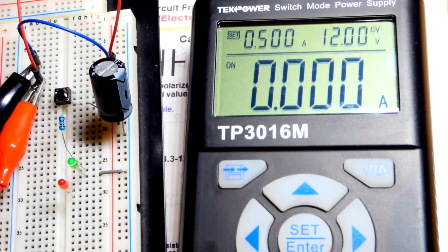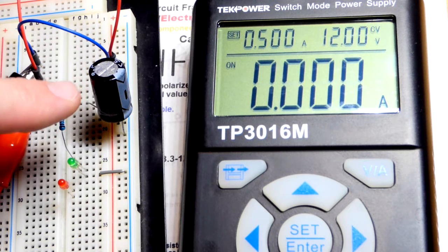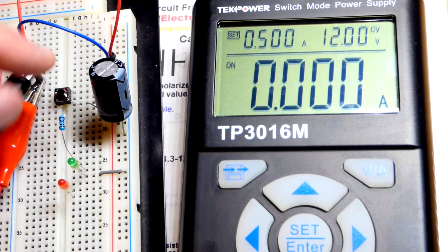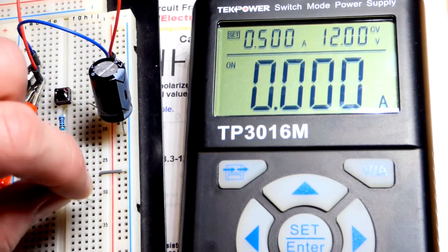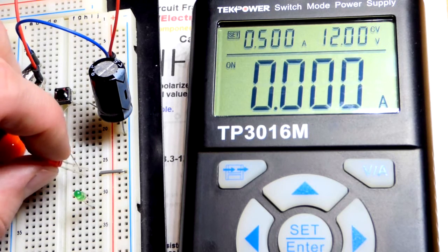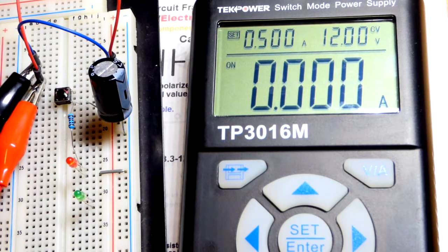The LED drops about 3 volts, and so it's going to probably discharge 9 volts down to 3 volts, and then probably level off somewhere around there. So maybe 2.5 or something. We could take those measurements later and see exact values. Now let's compare that with the red LED, which you're going to see it light up.